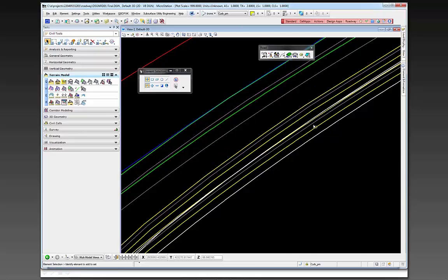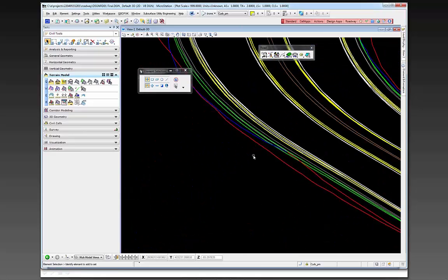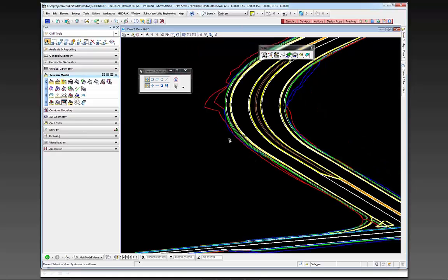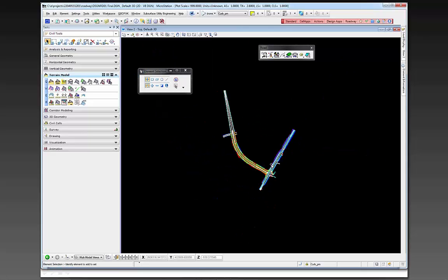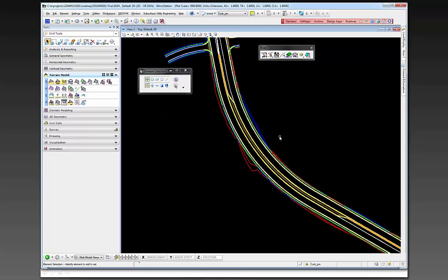There may be some lines out here that really don't represent what you're trying to do. In that case, you would just go through and use your judgment as to what the contractor would need as break lines, to either build the surface from the break lines or drape them onto the proposed surface so that he would have lines to follow.